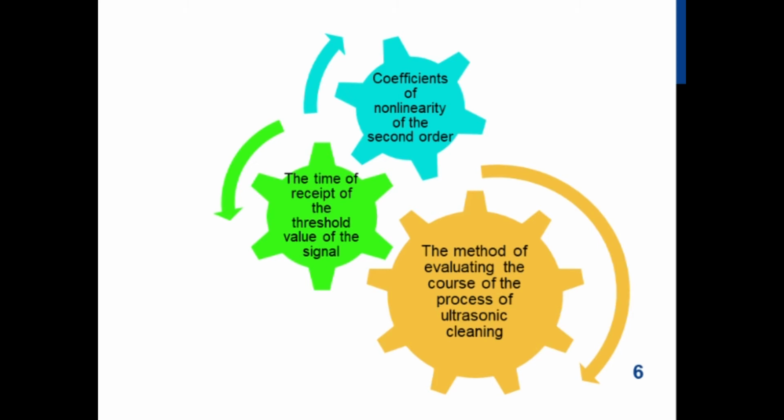Ultrasonic non-destructive evaluation is widely used to quantify the mechanical and structural properties of the body. It has established itself well in many industries and continues to expand its application. Existing studies indicate the feasibility of using it to determine the degree of heterogeneity of the mechanical properties of the body, coefficients of nonlinearity of the second and third orders.